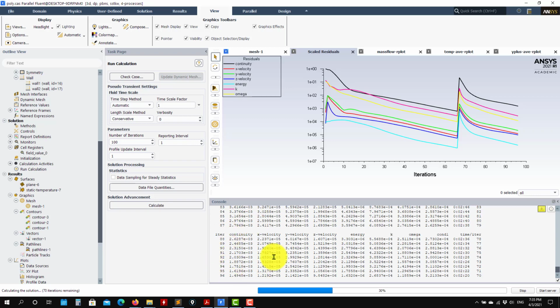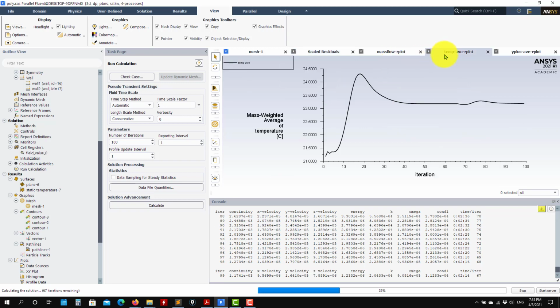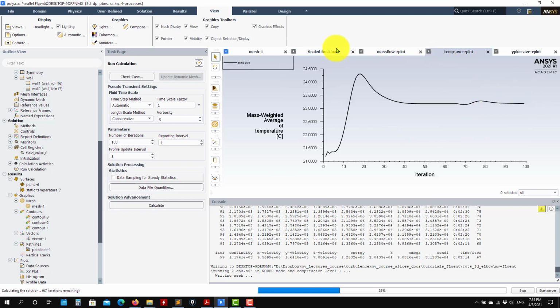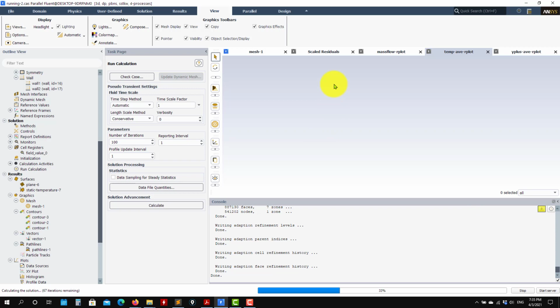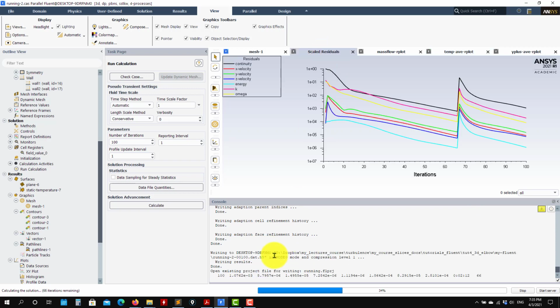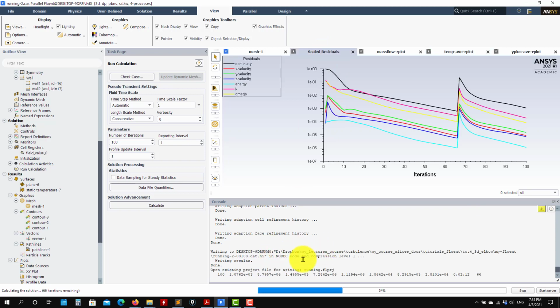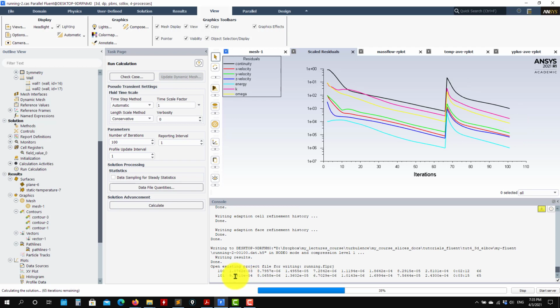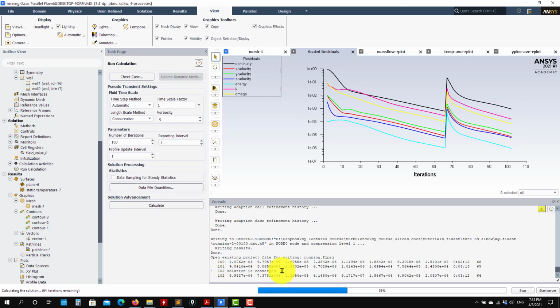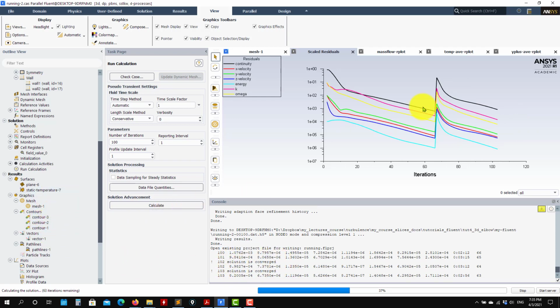So it will arrive at the convergence, at the tolerance of the absolute residuals here. But this monitor that we imposed here, you haven't reached this one yet. So see that it's saving, and it's almost there. So see here that it converged to the tolerance of the monitor.